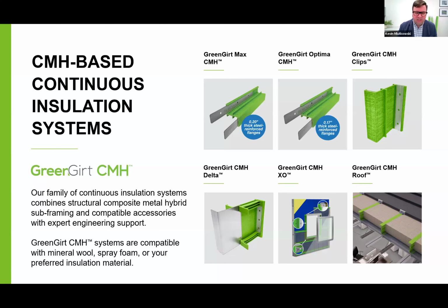The great thing about the Delta adjustable is you can see those dual grips on the right side of the bottom, holding that aluminum L in place and providing a degree of adjustability, up to 10.5 inches with our maximum systems as well. That allows you to accommodate any buildings that may have already been constructed where the walls aren't completely plumb. You can accommodate for that variance and ultimately have the cladding that's outboard be installed so it's perfectly flush, perfectly level. So those are our wall systems.